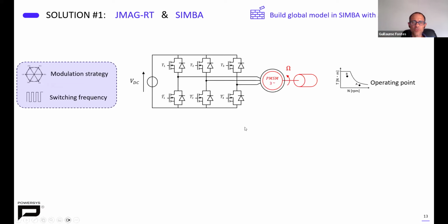For the inverter side, SIMBA can easily handle it, and a thermal description of power switches is used to compute the power switch losses of the inverter. This thermal description is provided as XML files, which can most often be downloaded on manufacturer websites.